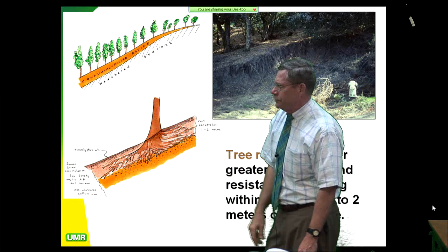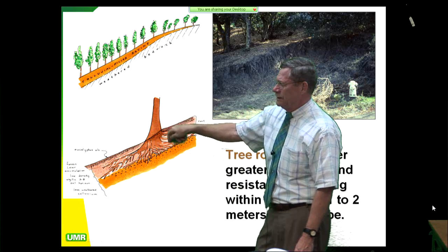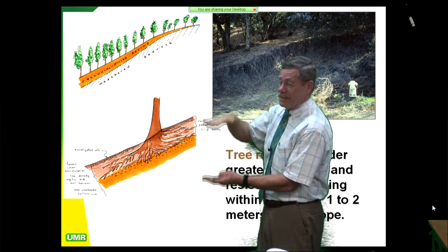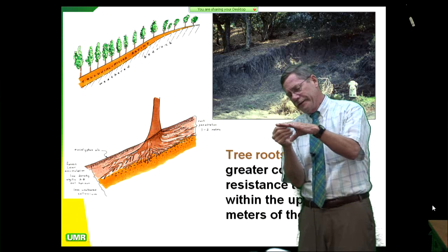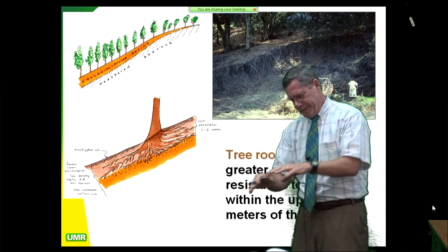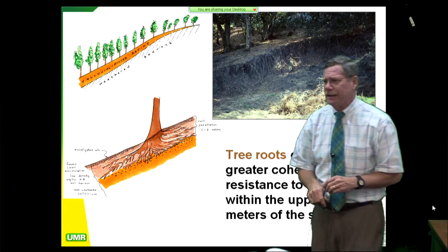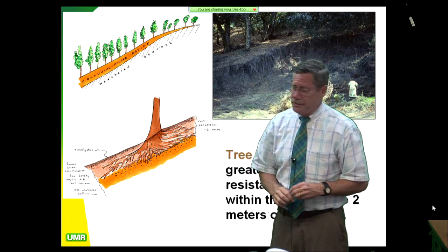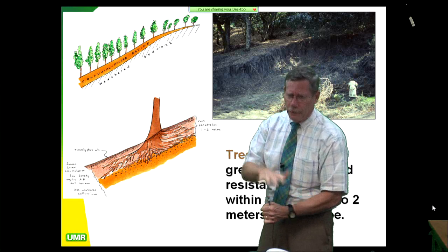you're in big trouble. Now this zone, by the way, is very hard to sample with drive samplers. When you're drive sampling in that rooted zone, you're going to densify the sample. So you better mark the barrel, say, mark, I did 19 inches. Okay? You pull the barrel out, you open it up, you measure, you're going to have 16. Yeah, you just densified it 3 inches. You're always going to densify when you do a drive sample and you're pounding a donut on it.